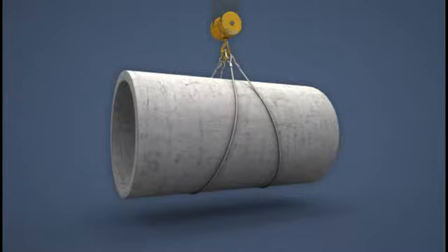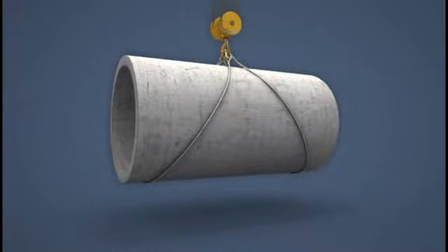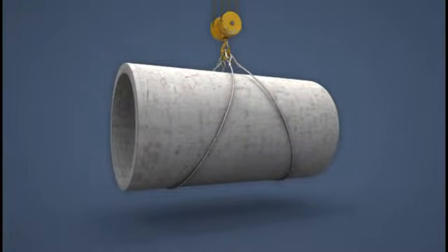In a double basket, the legs should be spread far enough apart to balance the load, but not so far apart as to create low sling angles. A low sling angle creates the possibility for the sling arms to slide inward.